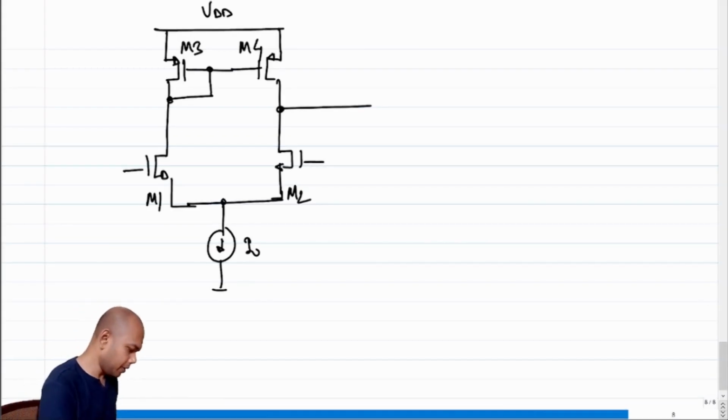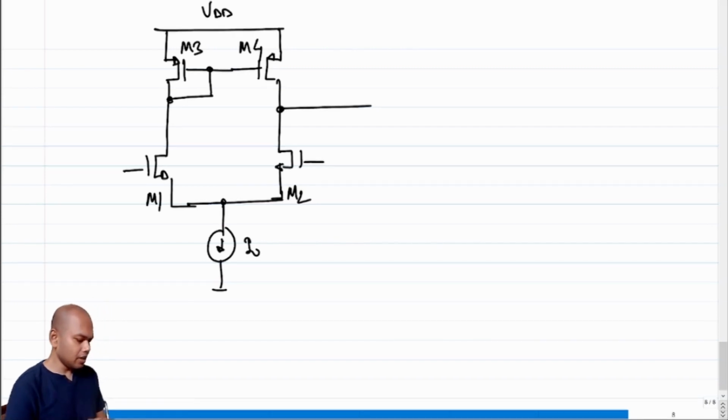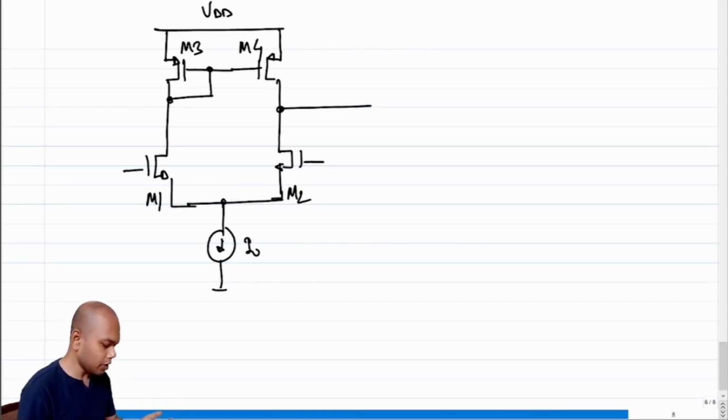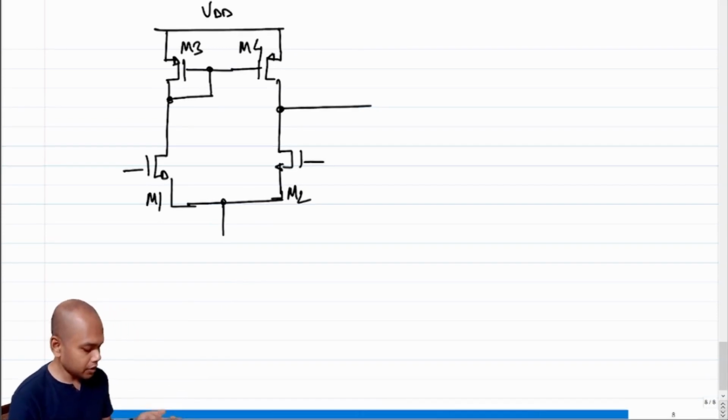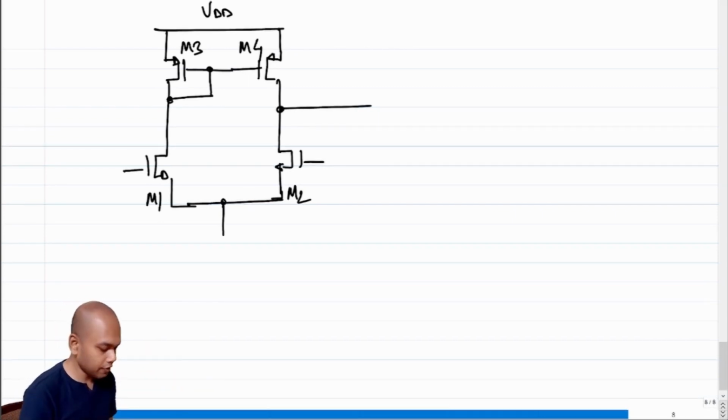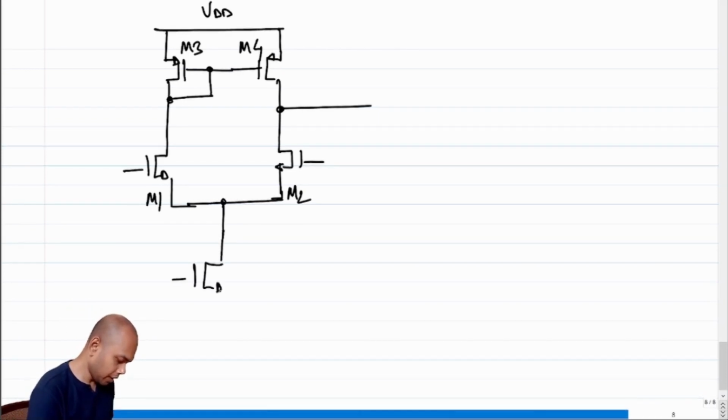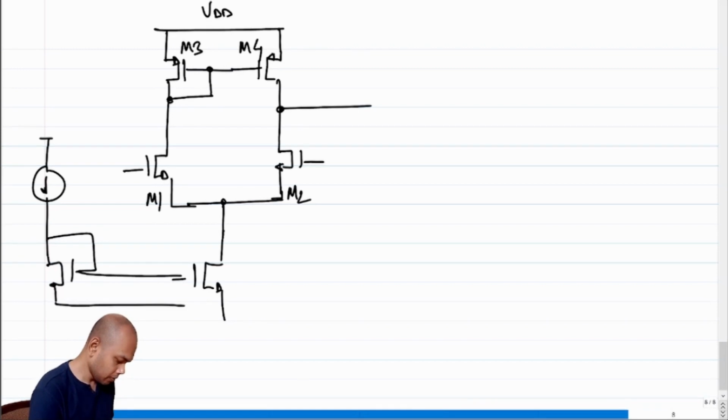Okay, so till now we have been dealing with this differential amplifier, and you must have noticed that I have used this constant current source at the source, and we had done that earlier also when we were dealing with the differential amplifier with resistive loads, and then we replaced the current source with a more realistic thing, and that was a current mirror based configuration.